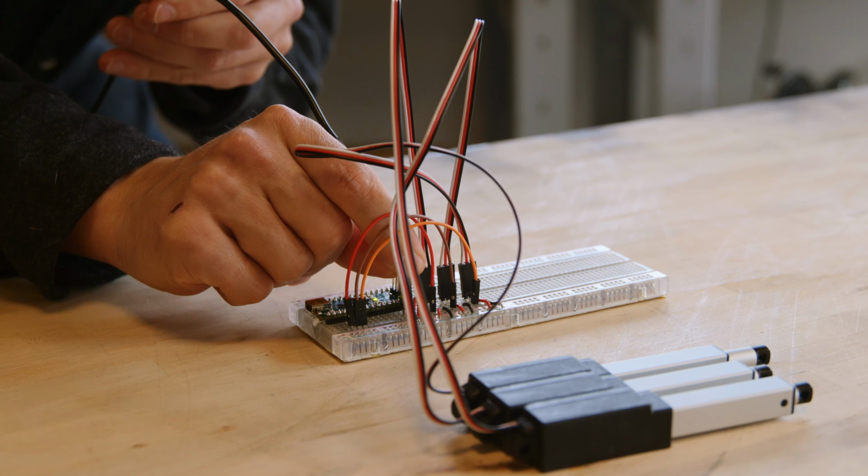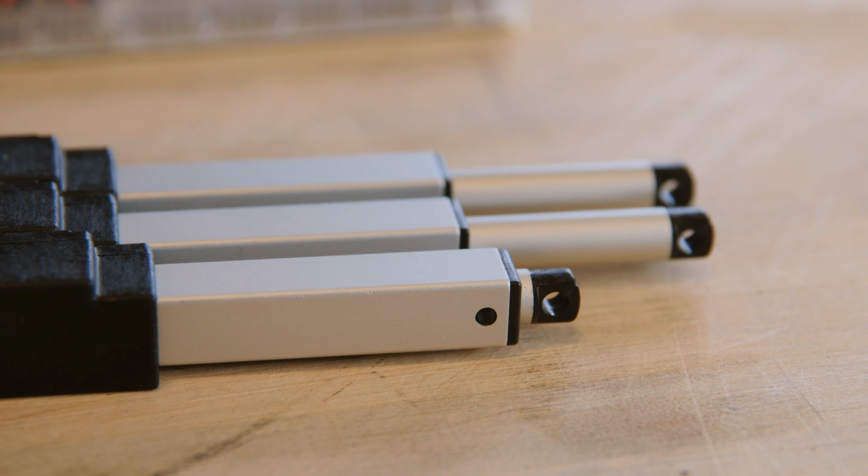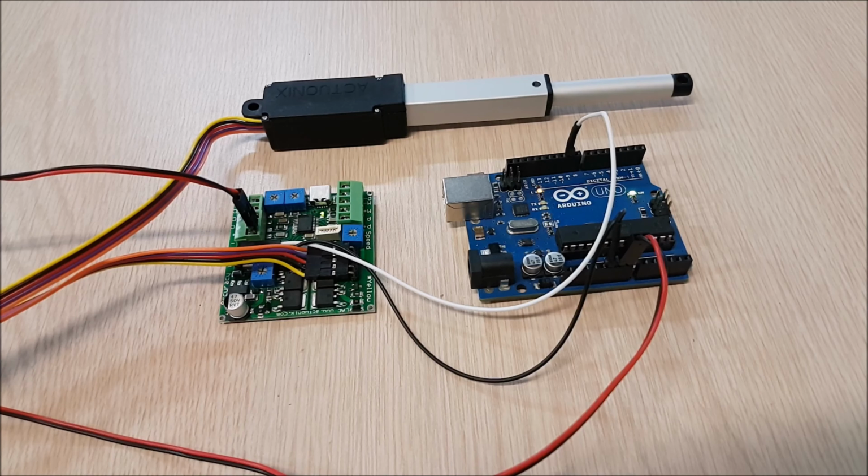Install the actuator in your target device or application. Try to conduct the test at an ambient temperature and humidity that would be average for your application. You can repeat testing later at extremes of expected if your average conditions test is successful. You can also adjust your test timing to speed up testing, but keep in mind some actuator models and operating conditions may be more sensitive to increased duty cycle operation, which could potentially skew your test results.